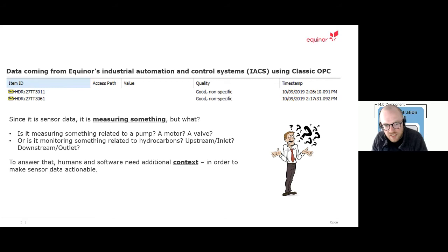And time series data and sensor data made available from all these industrial assets and field devices we have on the facilities and make this available to the IT world, to the IT platform for monitoring, analytics, optimization, decision support, etc. They have in the past been very simple. It's simply a tag name, a value, a quality bit and a timestamp. And if you are lucky, you get some additional metadata as well, such as a description and unit, but that is not always the case, actually.